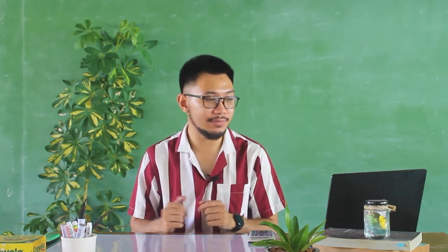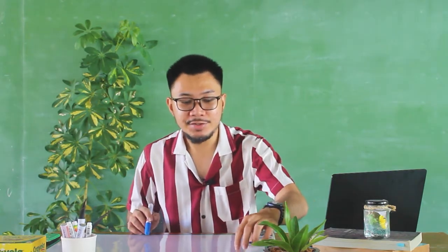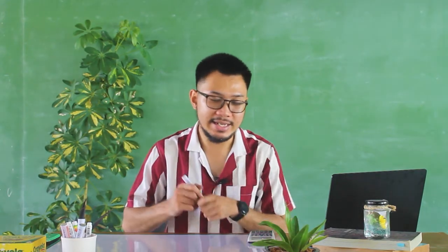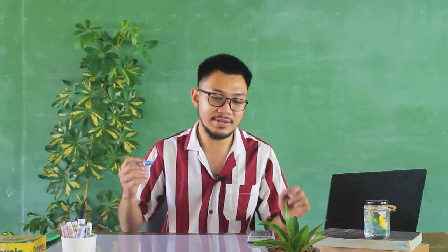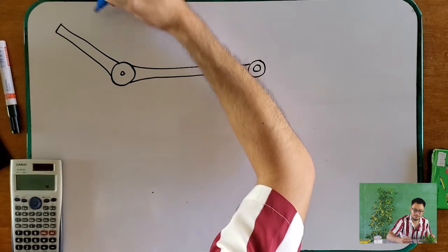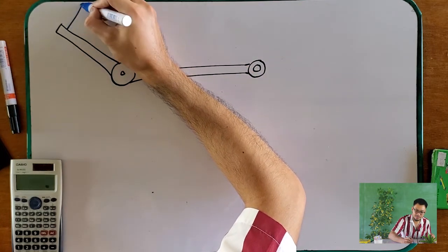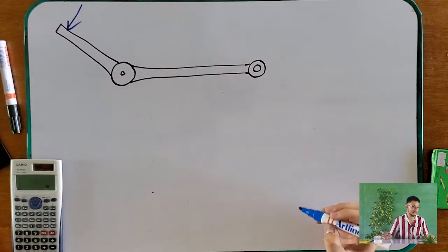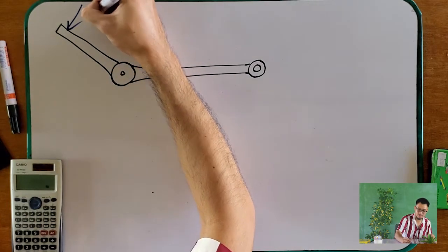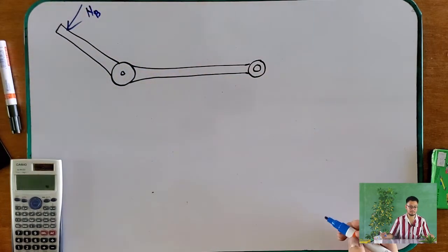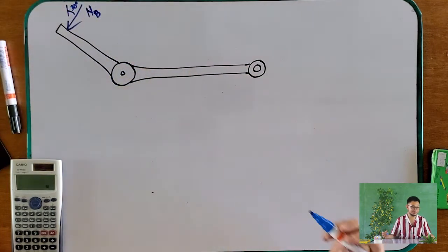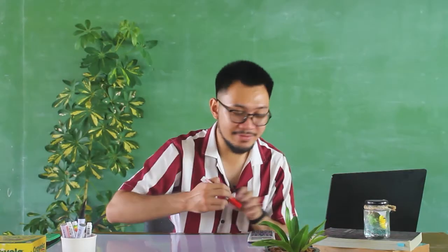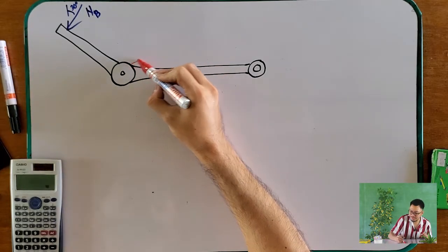Okay. So let us expose all the forces. Since this is a smooth support, and we said that for a smooth support the force should be perpendicular to the surface. So this is the surface here, so that is our smooth support. Okay? Let's call this one normal B. And that is oriented 30 degrees. Okay. We have a triangular loading here.